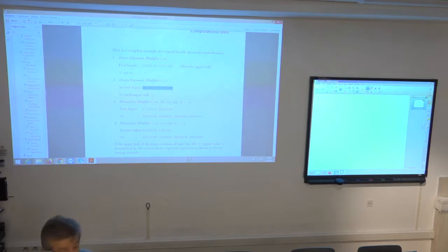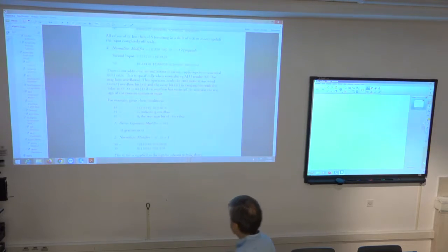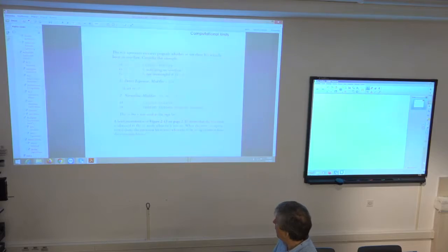So actually with 4 assembly instructions, you can perform exponent detection of a 32-bit value and normalization of this same 32-bit value by a given detected exponent. Okay? And there are several other examples here you can check by yourself. And that is, I think, the last page describing this barrel shifter.